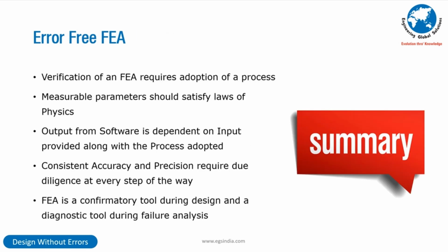So to perform an error-free FEA, verification of the FEA requires adoption of a process as given earlier. Measurable parameters should satisfy the laws of physics. Output from the software is dependent on the input provided along with the process adopted. Consistent accuracy and precision require due diligence at every step of the way. And then FEA is a confirmatory tool during design, and it's a diagnostic tool during failure analysis.